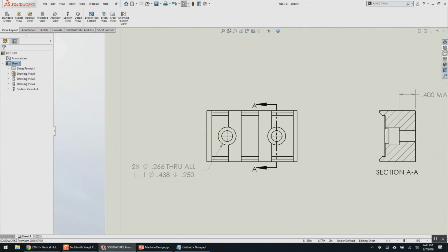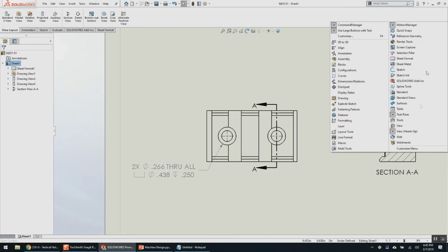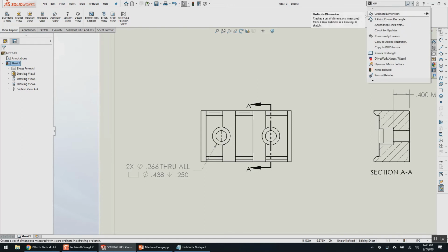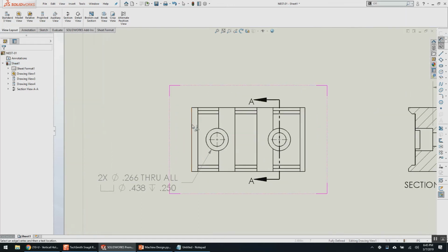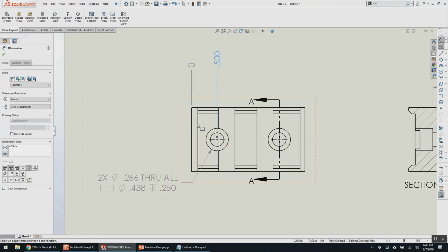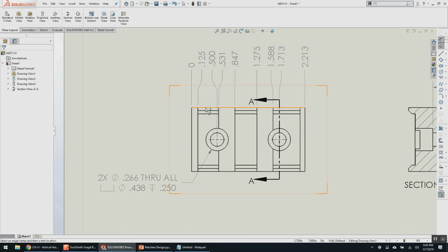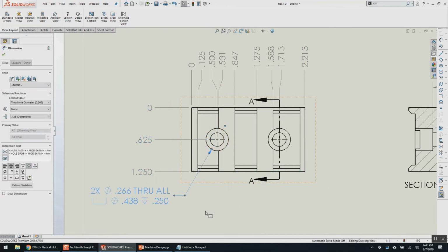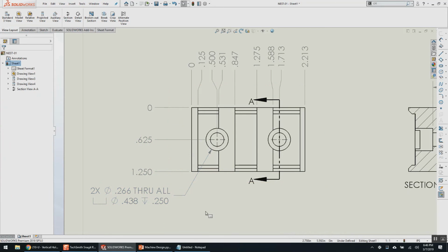From there, we'll do some ordinate dimensions. Where's my sketch toolbar? Again, I want ordinate dimensions, so I'm gonna drag this right below my dimension tool because I use ordinates a lot. I always ordinate off the upper back left corner because, who wants to tell me why? Because that's how machinists set it up, right? The back of your vise never moves. Well, normally, typically, the back jaw of your vise never moves, the front jaw moves to the back. And if anybody ever sets up a vise stop, the vise stop is always on the left because normal people are right-handed, left hands are freaks.